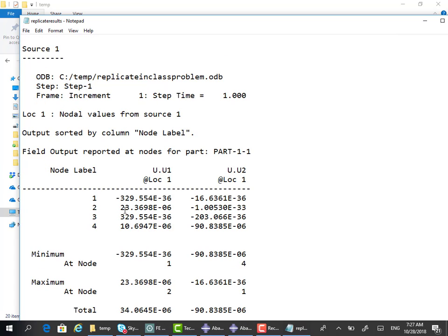So these are the results. Remember, we're not going to get the same node numbers, but we should get the same results. First let's look at node 1, which was the origin. It's a numerical problem, so it should be 0, 0, but numerically it's close to 0, according to the solver that Abaqus had. So we can just say these are zeros. Then let's look at the displacement in the x direction of that second node that has a roller.